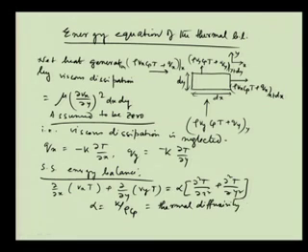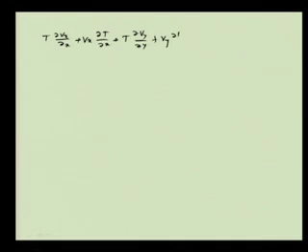Okay. So, this is what is happening. Now, what we will try to understand is, if we further go ahead with this equation, then we will have that T into ∂Vx/∂x plus Vx into ∂T/∂x plus T into ∂Vy/∂y plus Vy into ∂T/∂y is equal to alpha into (∂²T/∂x² plus ∂²T/∂y²).